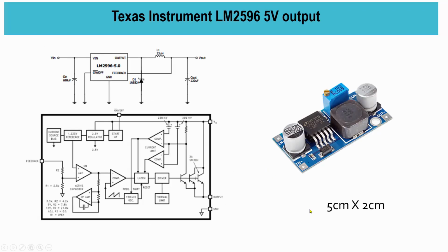This is one example, and the IC component is the LM2596 if you're using the -5 version. All you need to do is get this IC and, with only a few components, 1, 2, 3, and 4. The C is the input capacitor, which filters the ripple current that kicks back into the source.